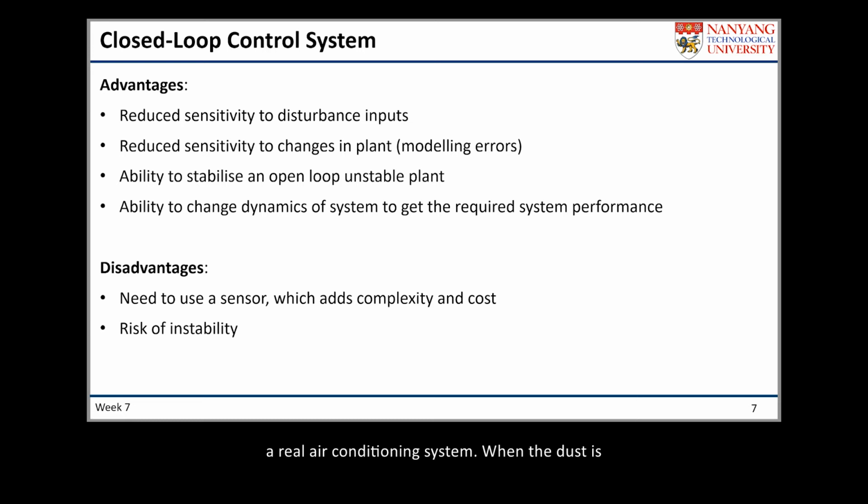When the dust is piling on your heat pump, then the controller logic, if you have a good air conditioning system with a good controller, will ask the heat pump to take more heat when the heat pump is not performing well. So there is a way to regulate the heat pump through the controller in your air conditioning system to reduce the sensitivity to the disturbance.